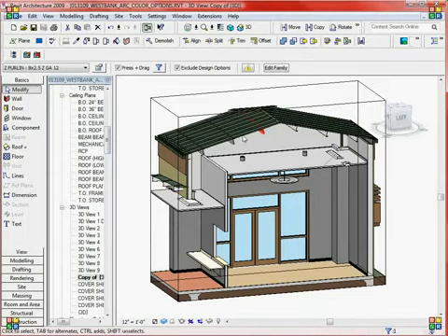Further, these materials are attached either to one another or to a reference plane, and whatever changes are made, that material will follow with it, with the proper settings. Even further, if we were to change the slope of this roof, all these materials, the structure, everything would follow with it.